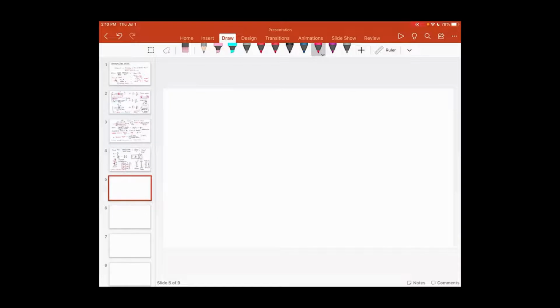So what I will do is I will take these numbers and I would plot those on a graph paper. So on x-axis, I'm going to have strain. On y-axis, I will have stress. And you would realize that as I start plotting these points, I get a particular type of curve. This is called as the stress strain curve for mild steel.